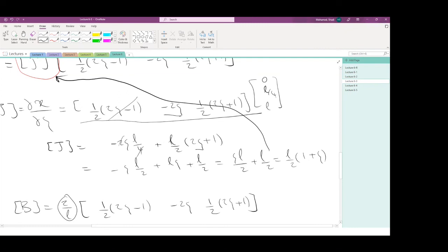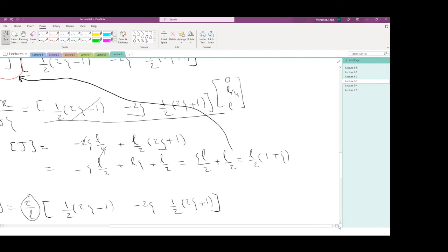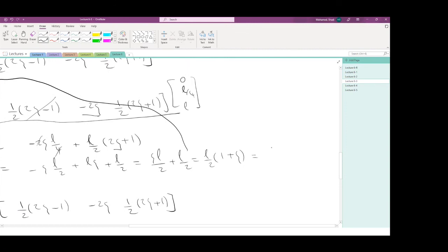Now, the Jacobian matrix is going to look like this. And you can start to see that this is not an obvious scaling process, just like we did in the past. So this is slightly different. Before it was L over 2 when you had the node at the center. If you shift the nodes, there will be some function of psi happening in there.